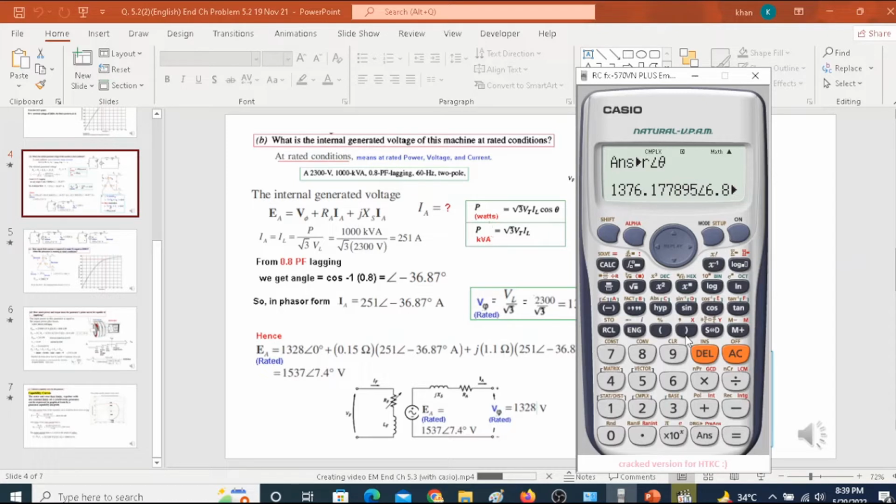Also, when we talk of power, the power is actually 3 multiplied by the phase power, and phase power can be written as V phase, I phase and cos theta when we are representing the power in watts, which is the case on the output side of the circuit. Now for Y connection, V phase is actually V line divided by root 3, and so our equation will become this equation. Now you can remember this for whether it is a delta circuit or a Y circuit. This is the formula for total power.